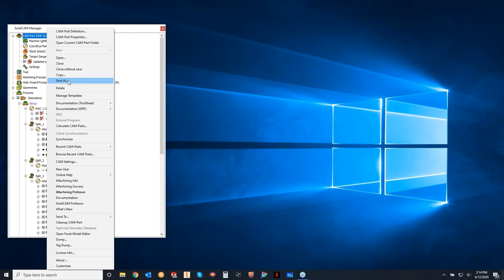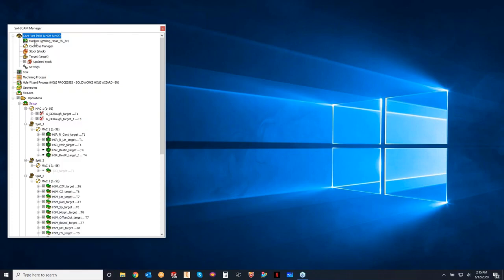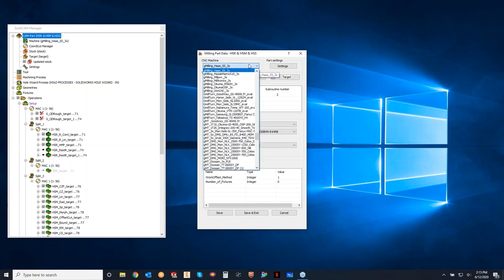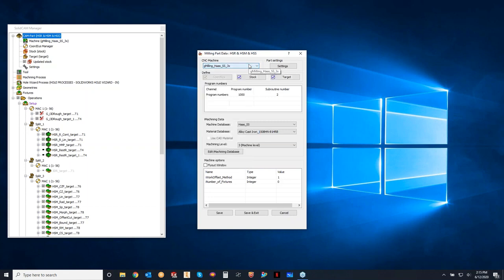Yeah, and to go ahead and double click where it says CAM part to get back to where the coordinate system and stuff are. Another nice feature is, Brad thought he was going to machine this on the Haas. Well, Joe got down on the shop floor and said no, I'd rather run that on the different machine. So you can go in here and switch out machines as well. So different post processors also. Yep. As well as switch out your stock.